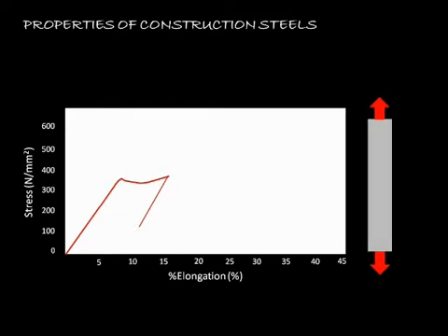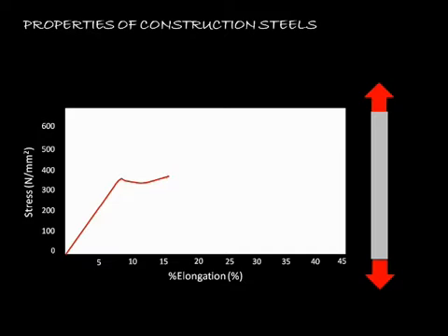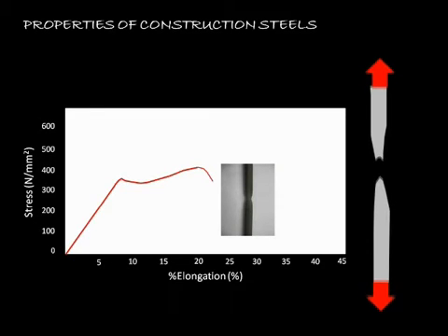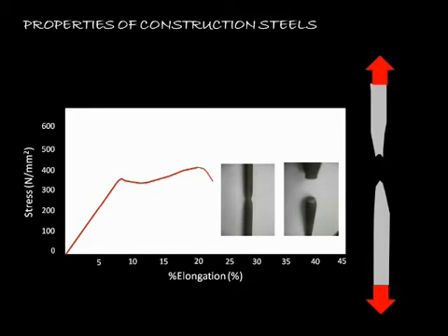Reapplying the load, the stress-strain plot picks up where it left off. From this point onwards, as the steel bar is elongating under load, an increase in stress is noticeable. Dislocations within the microstructure are tangling up and causing this increase in stress. At the end of this section, the ultimate tensile strength is reached, followed by necking of the steel material and then failure. This is a ductile steel, and examining the failure specimen, it looks like a cup on one side and a cone on the other.